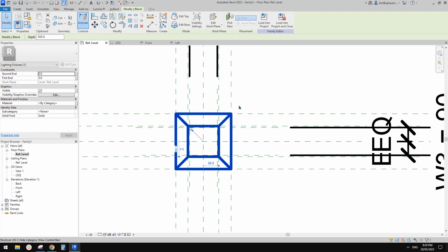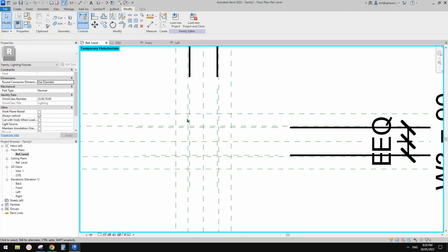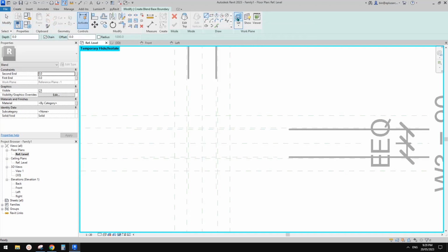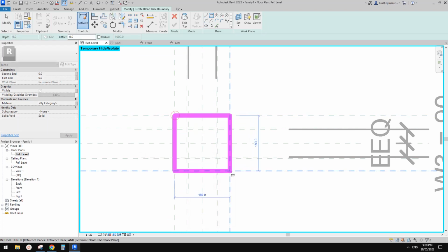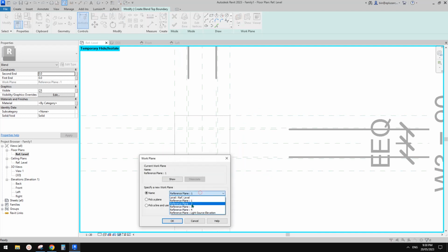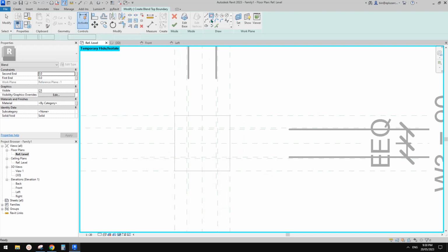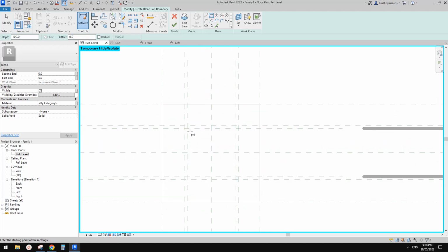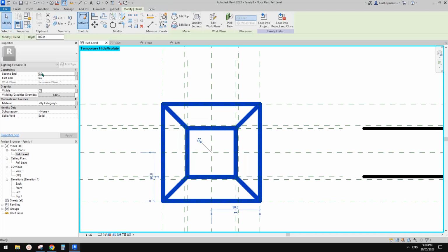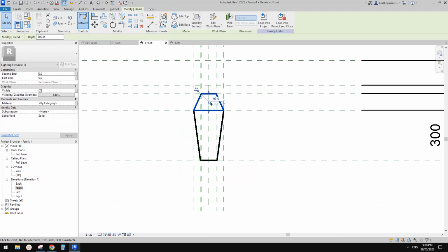To make it easier, I'll just temporarily hide it, and create blend. Set work plane, currently 1, correct, and rectangle here to here. Yep, just lock them. And Edit Top, Set Work Plane, change this one to 2, okay, and once again, this time it's the 190 mil, so these, and then 1, 2, 3, and 4, and then finish, so 0, 0. Go to front view so you can see that's it.